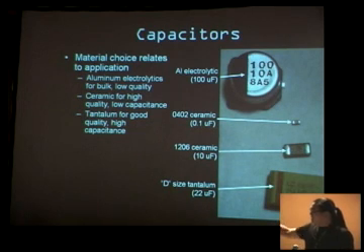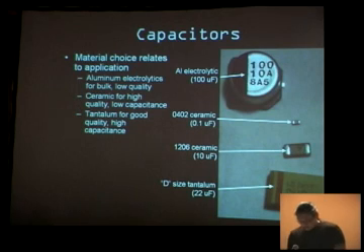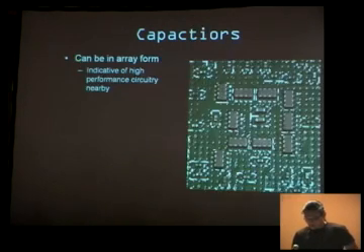The ceramic capacitors, the 2 in the middle, are like the hot rods of capacitors. They're very, very fast. They're very capable capacitors, very stable if you get the right dielectric. And typically if you see those, they indicate that there's some very fast, maybe interesting circuit going on. And the bottom one is called a tantalum capacitor. It uses a more expensive substrate. They have good quality and high capacitance, and are typically used for power supply decoupling, although they have a reputation for exploding in a wonderful, brilliant white flame if you hook them in backwards or put too much current through them. So a lot of Japanese equipment will not use tantalum capacitors because it's too embarrassing to have exploding capacitors in their electronics, and they will avoid using them at all costs.